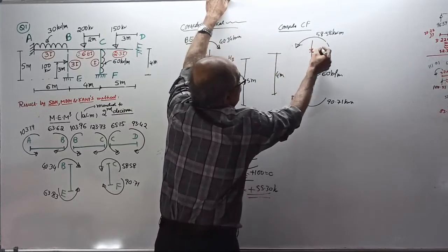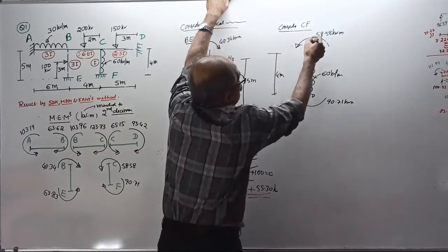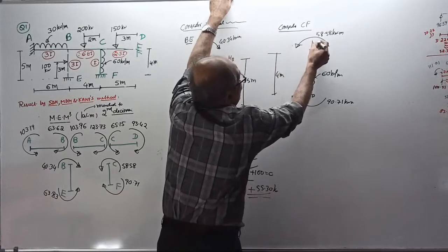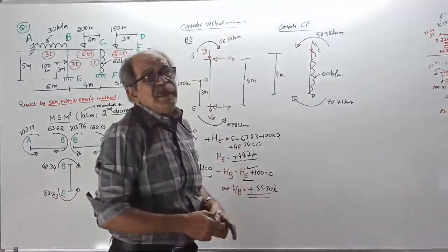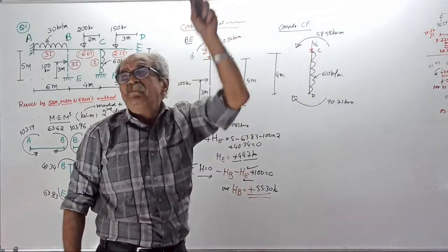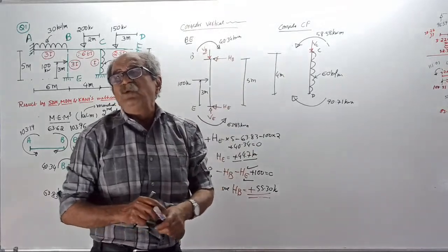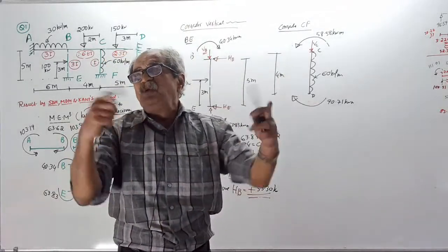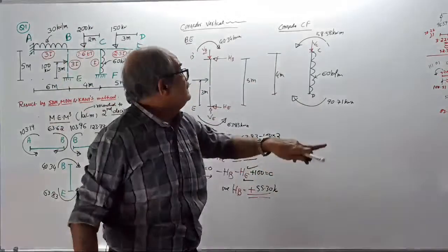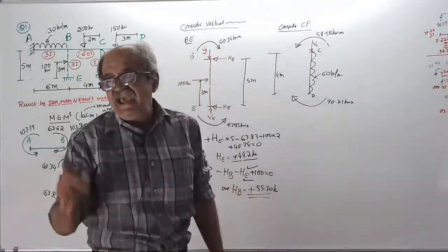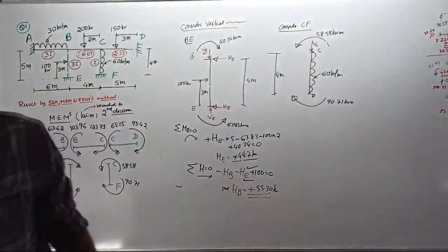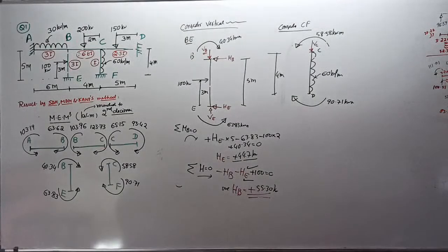Then there is going to be a vertical reaction down here. This is C, this is D. A vertical down, I will call VC. This VC will be equal to that beam's VC1 plus VC2. VC1 plus VC2 is upward, reverse it, downward, it will give compression. Clear? Those who are in the group, clear? The sum of those two reactions will be transferred here.